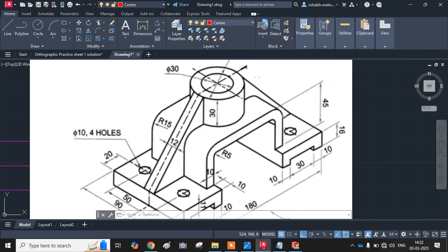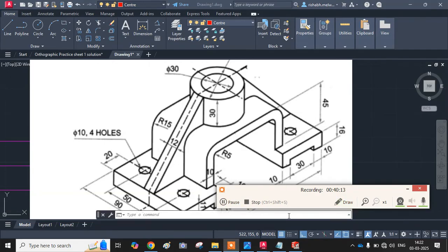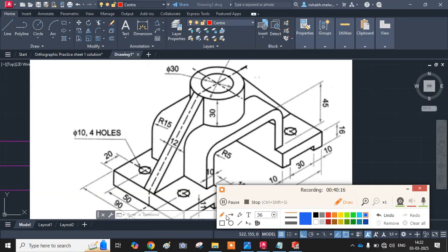So this fillet, if you see, its center will be here, okay, and this fillet's center will be here. I will show it with the help of some color. See, if you observe this part of the fillet, what is the radius? 5, so its center will be over here somewhere, and then 10 is getting added, so if you see this fillet from this point, what will be the radius? 15.